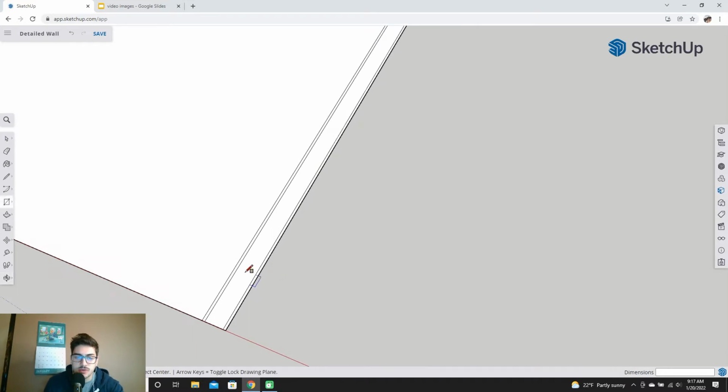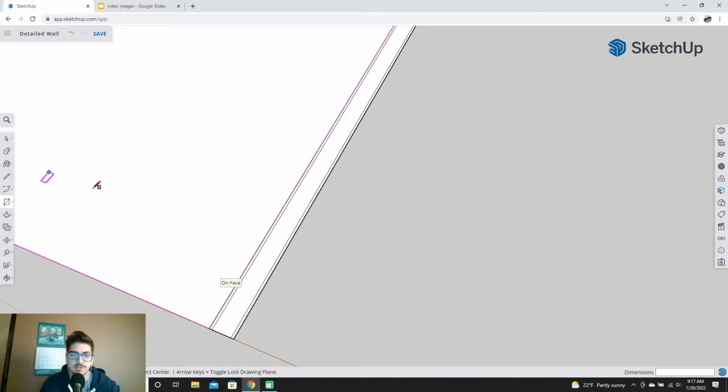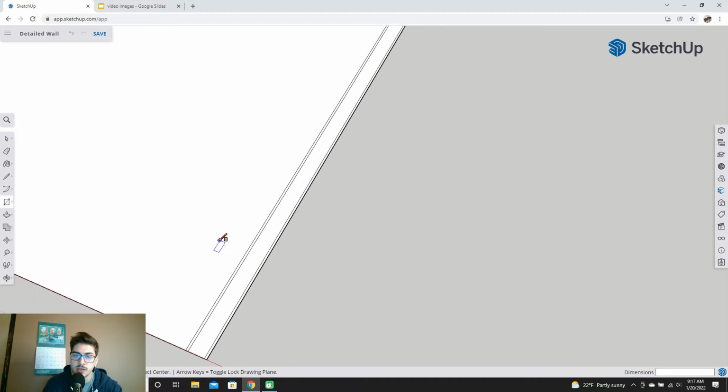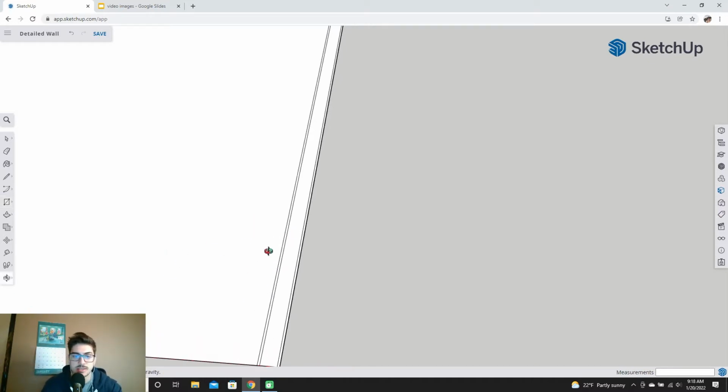Okay. And you may have noticed when I put in the stud, which is a 2x4, right? That's the normal stud that gets used inside walls, especially non-load bearing walls. Well, it's important to be familiar with the fact that those are actually 1.5 by 3.5 inches dimensionally, because they get carved down from the raw 2x4. So if you're working in a house that's 100 years old, maybe you have actual true 2x4s. But anytime you're putting in modern studs and it's 2x4 walls, it's actually 1.5 by 3.5. You can Google that. I'm not lying to you.